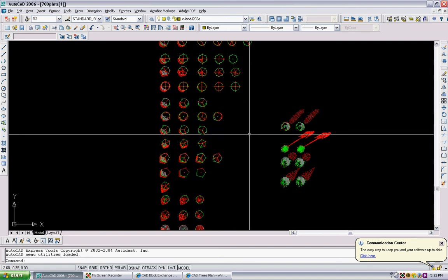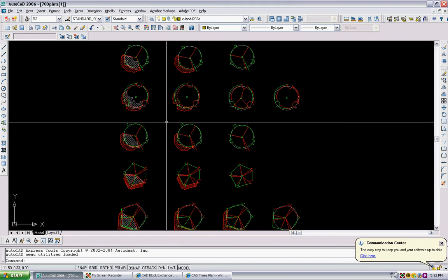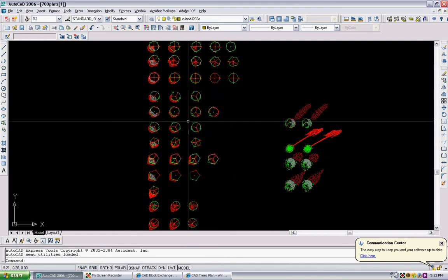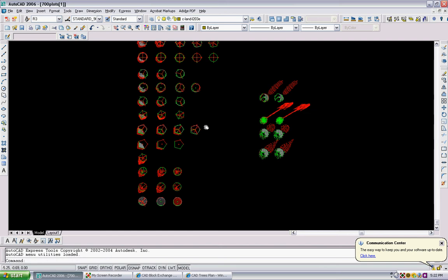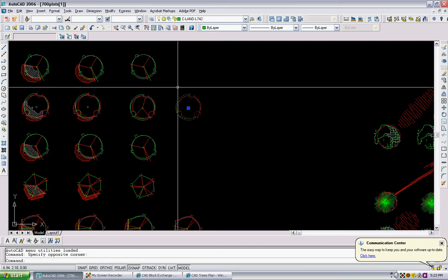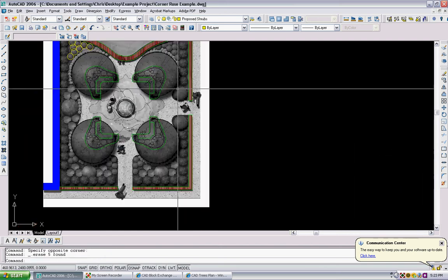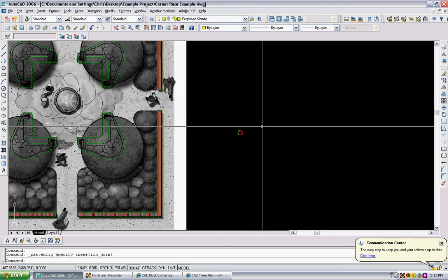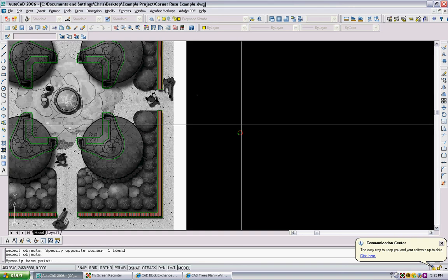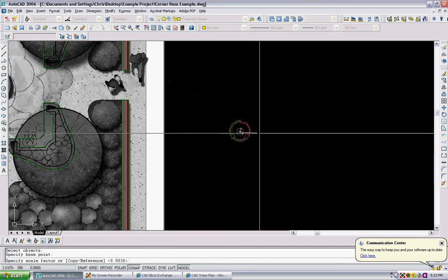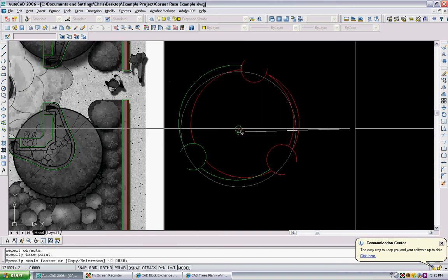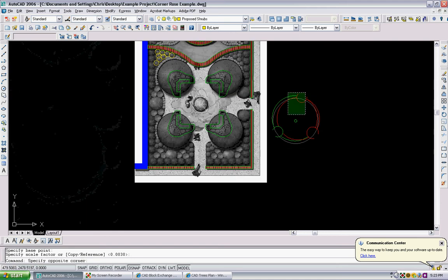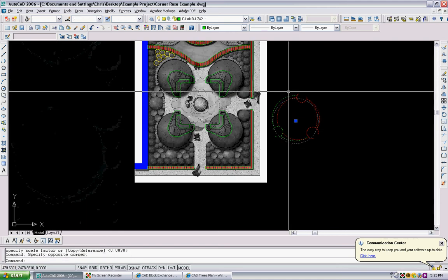But then, as far as production and stuff, it's all about getting your idea out there and making things short, and making sure your graphics are tight, legible, and convey the idea. But anyway, do the same thing. If you want these trees, you can copy one and bring it back over to your drawing, press Control V and put it in, and then you can scale it. Base point, I'm just going to bring it out, and whatever you wanted, you get your trees.